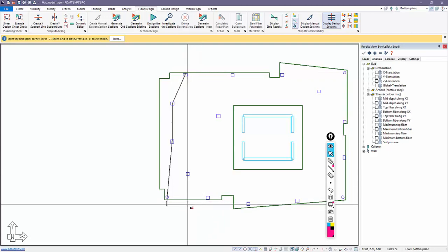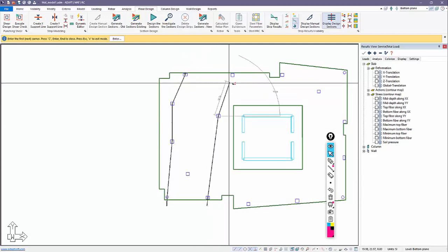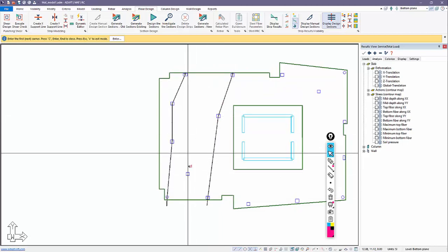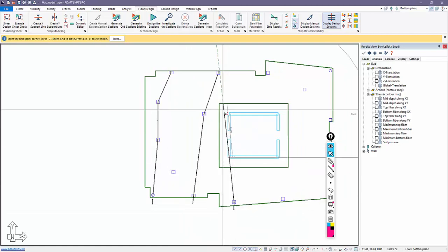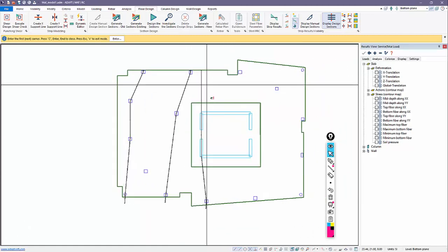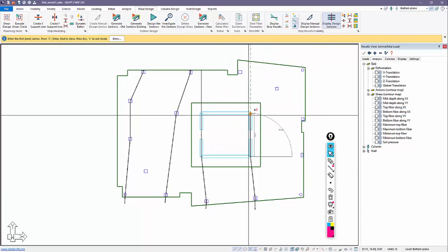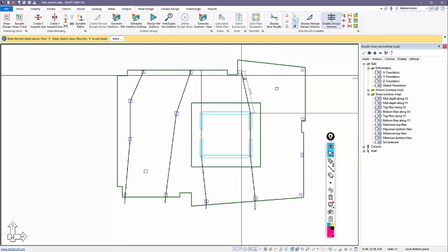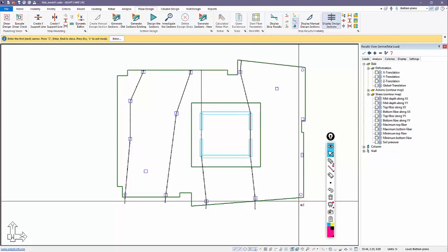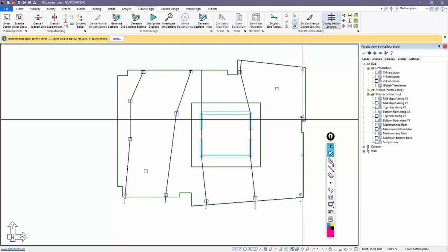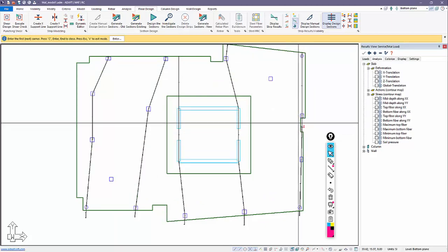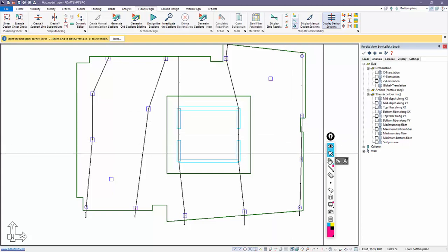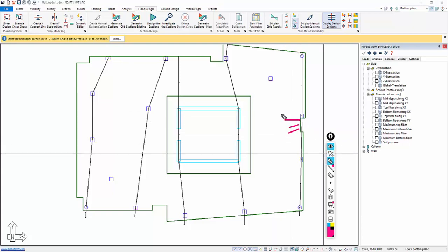Okay. We'll have a middle strip generated along that column again, so we'll leave that column as is. Just snapping on the endpoints of the walls there. And for this one, we're just going to go right through that opening. Why am I going through the opening? Well, the purpose of strips is to generate design cuts. So really all we want are design cuts aligned, somewhere out here to produce a result for this region.